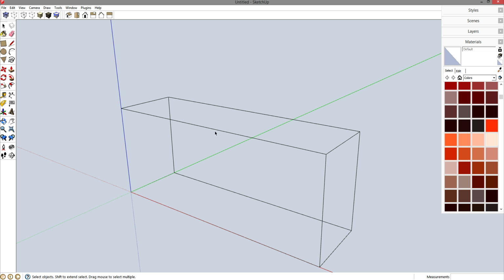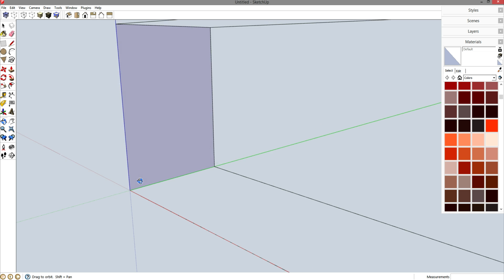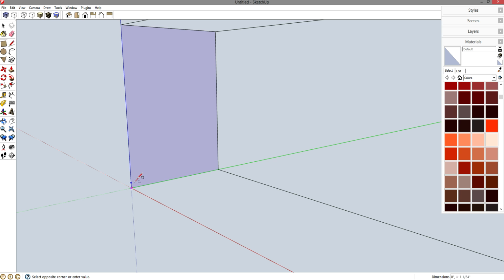Let's draw the outside panels first. R for rectangle, and I'm going to draw this side. I also have a little toe kick down here, so R for rectangle, and I'm going to go 3, 3. I don't know if there's a standard dimension for this toe kick, but I've always just used 3 inches. That seems to do the job just fine. So let's click and delete that, and I've actually got a vertical line I need to delete and a horizontal line I need to delete.